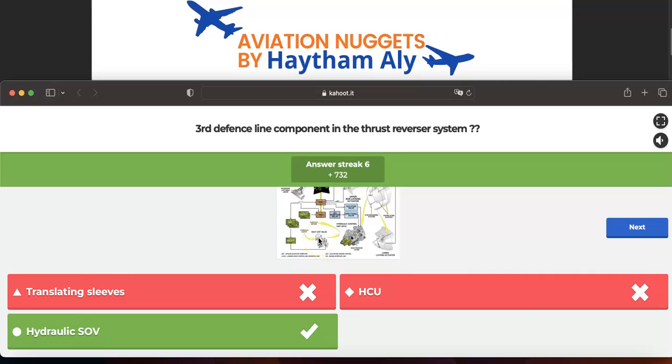Who opens the shutoff valve? The spoiler elevator computer, as an airframe system computer or an independent line of defense. The spoiler elevator computer will be commanded by a potentiometer inside the throttle control unit when the throttle lever angle is less than -3.